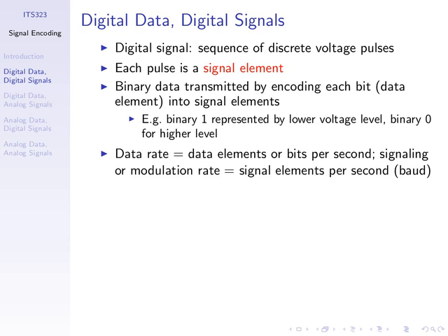So we recall the difference between data rate and signalling rate, and this is about the number of levels. When we refer back to the Nyquist equation, M was the number of levels. Increasing M increases our data rate when we keep other things the same.